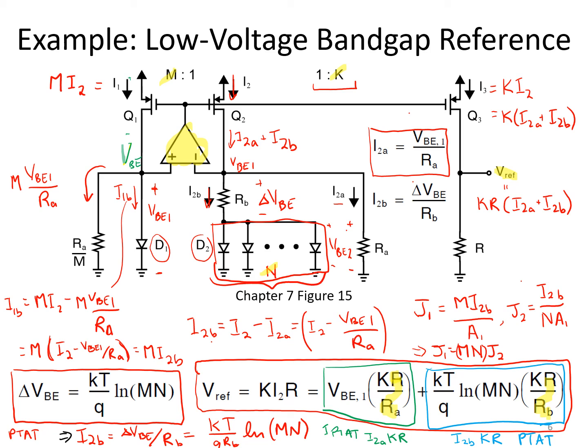And then you can perform simulations of the overall circuit, sweeping temperature to ensure that the output voltage Vref remains relatively constant across temperatures. You'd likely also want to check things like the sensitivity to supply voltage variations, and of course, stability of the feedback loop formed by the op amp.